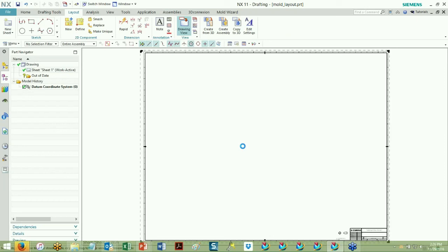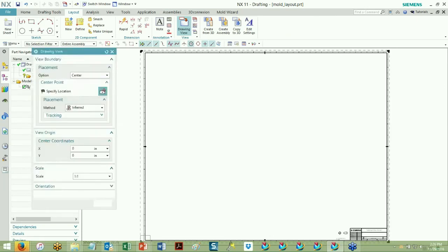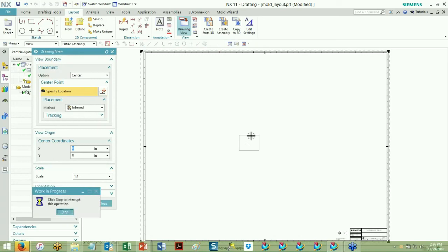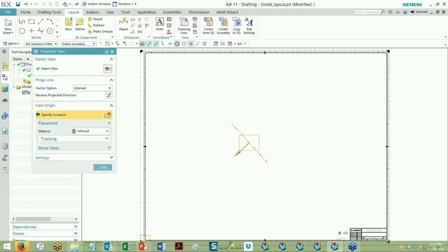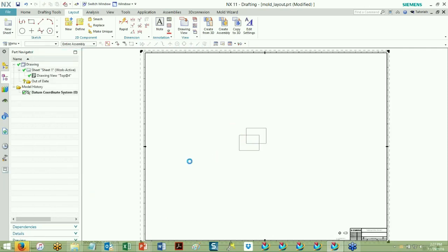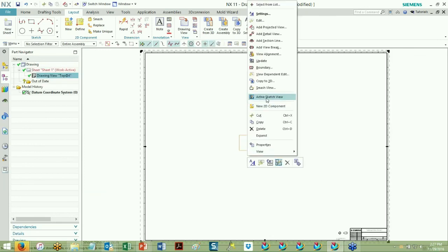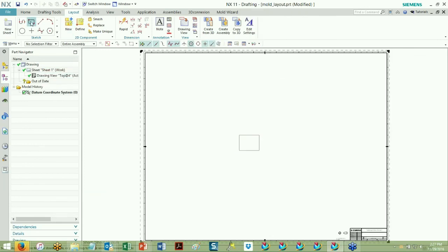And as you make that the active view or active sketch view, then you're going to see that it can be immediately, and what would you say, automatically updated as soon as you create curves within that generation. So we're going to get out of the projected view, make this the active sketch view, and just show you a quick rectangle.